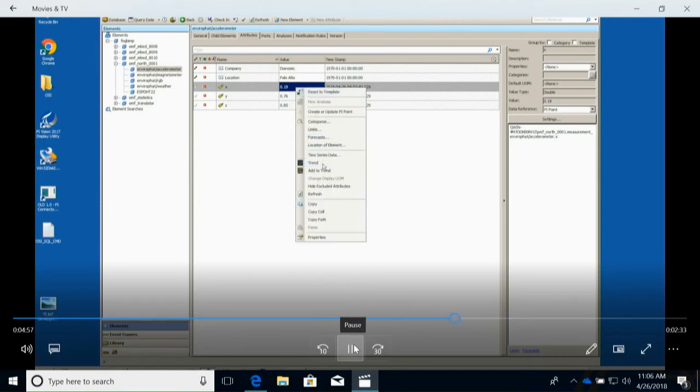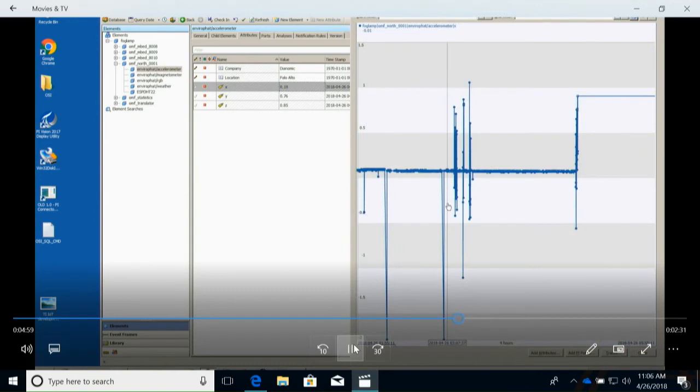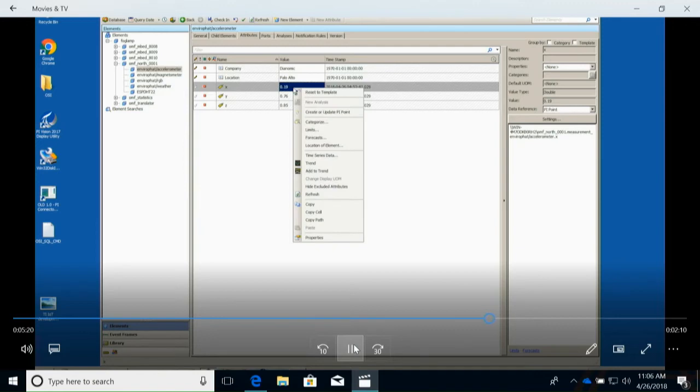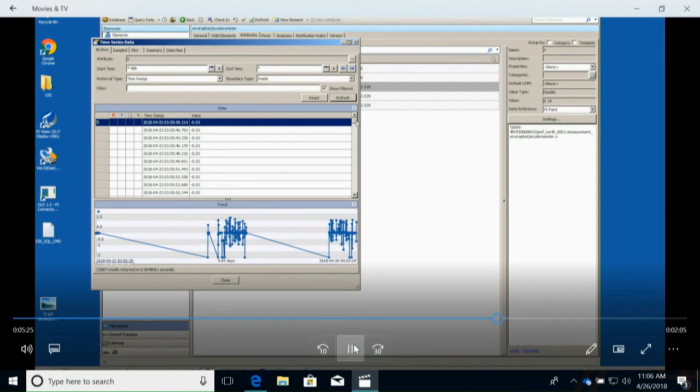Once the data from FogLAMP is in your Pi server, it is indistinguishable from any other data that may have been read into Pi. It will, however, remain within the FogLAMP buffer and may be sent to other Pi servers. FogLAMP provides mechanisms by which control can be exercised over how, when, and with what bandwidth utilization data is sent to Pi. This is particularly useful in applications where you have less than reliable connectivity or you have bandwidth constraints due to cost constraints or other issues.